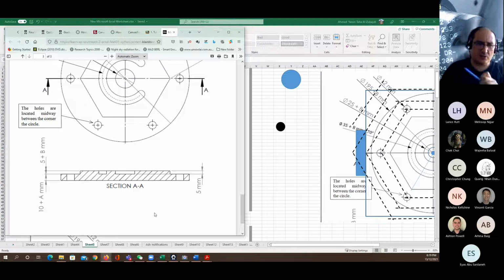I think that we talked about this one earlier in the manufacturing subject. I'm going to repeat that once again. When you're doing the rough cutting, the depth of cut is going to be high, the RPM value is going to be low, and the movement of the cutting, what we call the feed rate, is going to be high.